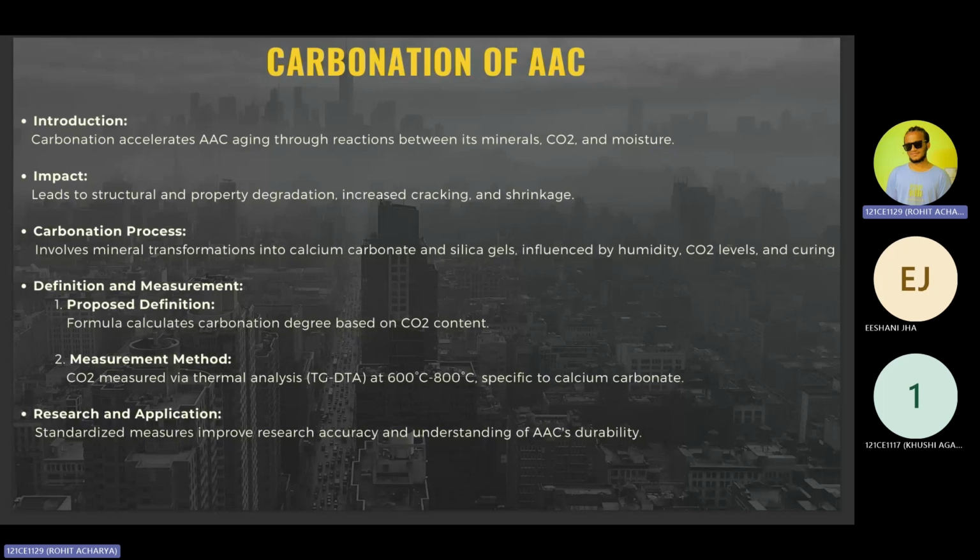For understanding what actually the carbonation process is, I will take you deeper into it. The carbonation process involves transformation of minerals within AAC into calcium carbonate and silica gels. These changes are influenced by environmental factors such as humidity, carbon dioxide levels, and the specific curing condition of AAC. This transformation is at the heart of why and how AAC changes over time.